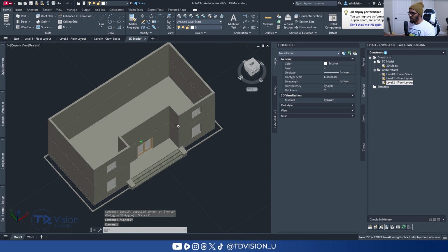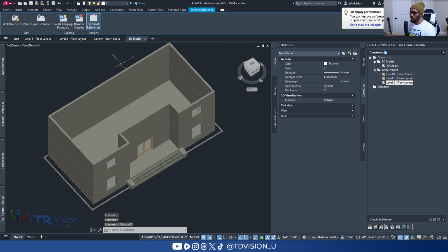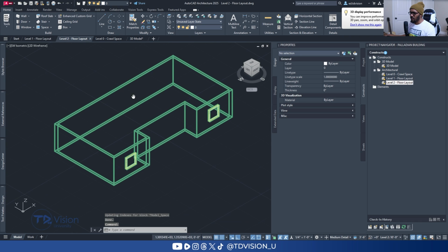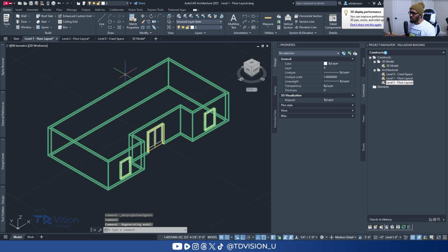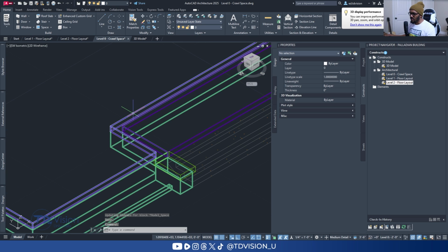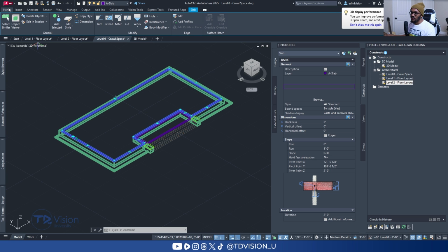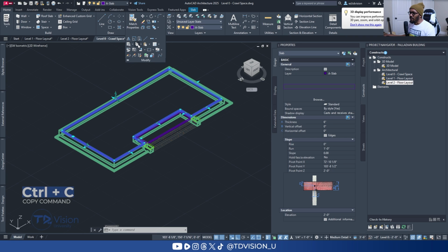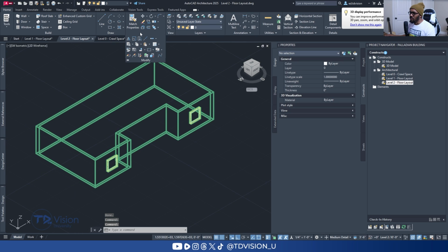And so the first thing I'm going to do is the floor. So for this level here, we need to go back to that construct, which is this, and add it in here. But if you remembered, if we go to level 1, we do have a slab in here. Actually, not level 1, it would have been the crawl space. Yeah, I'm going to just copy this slab since it is pretty much the same shape as the rest of the building. So I might as well just copy this one. So let's go ahead and do a copy on that, and we're going to go up to level 2 now and do a paste orig.